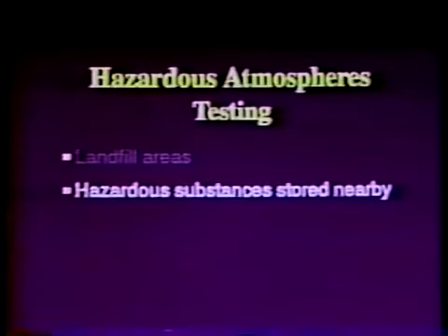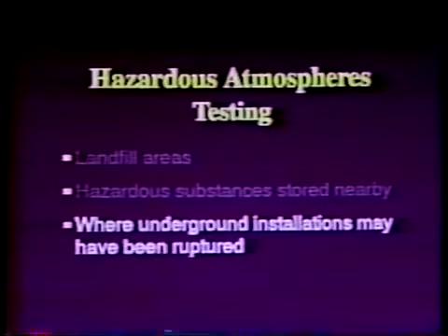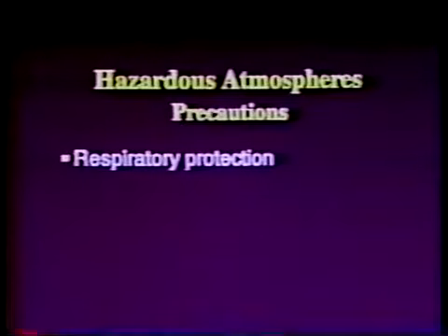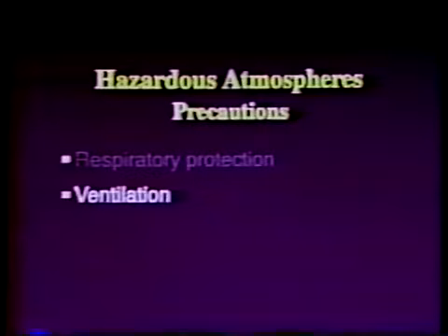Examples of these conditions include excavations in landfill areas or where hazardous substances are stored nearby, or where underground installations may have been ruptured. Adequate precautions shall be taken to prevent employee exposure to atmospheres containing less than 19.5% oxygen and other hazardous atmospheres. These precautions include providing proper respiratory protection or ventilation.